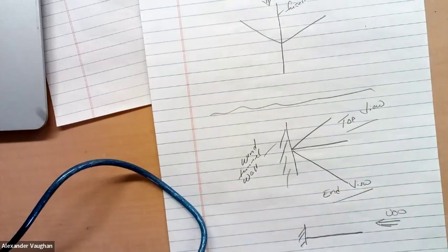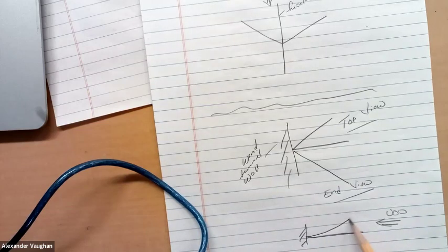So nothing much happens. It just sits there until I get to the divergence speed. That's not quite true because you can't align it perfectly. So there's a little bending from the non-alignment, right? It could bend up, it could bend down, but it's very small. And then when you get to divergence, you begin to get a bending like this.